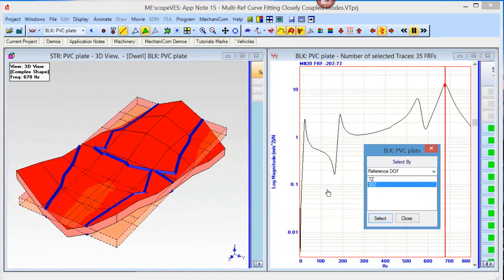I would call it a torsion mode, but we can always identify every mode by its frequency, what we call its natural frequency. That frequency will not change and the shape will not change unless some physical property of the structure changes or the material properties change. So either the boundary conditions, the physical shape, or the material properties have to change. Otherwise, a resonance or a mode of vibration will not change.